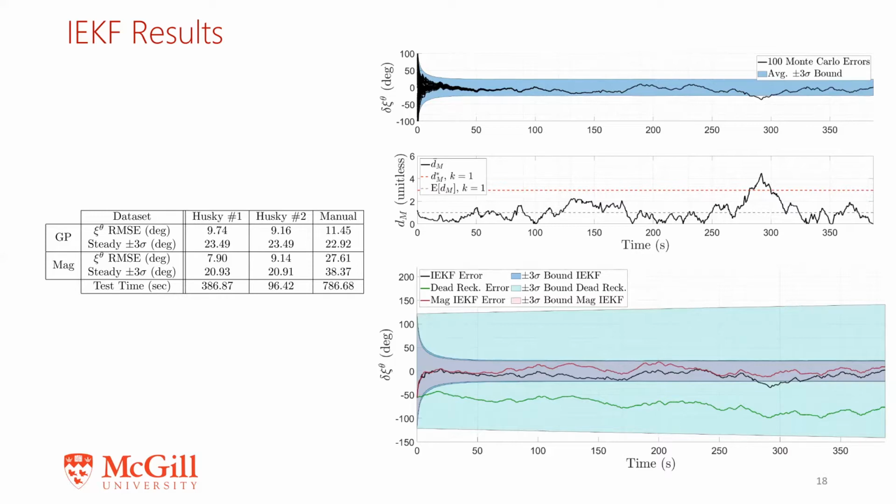As can be seen in the table summarizing our results, our method produces a heading estimate within 10 degrees of accuracy, which is comparable to the performance achieved using a magnetometer IEKF. Since the magnetometer IEKF would still likely use a UWB system for positioning, our approach effectively achieves comparable performance while using one less sensor for a position and heading estimating indoor robot system.